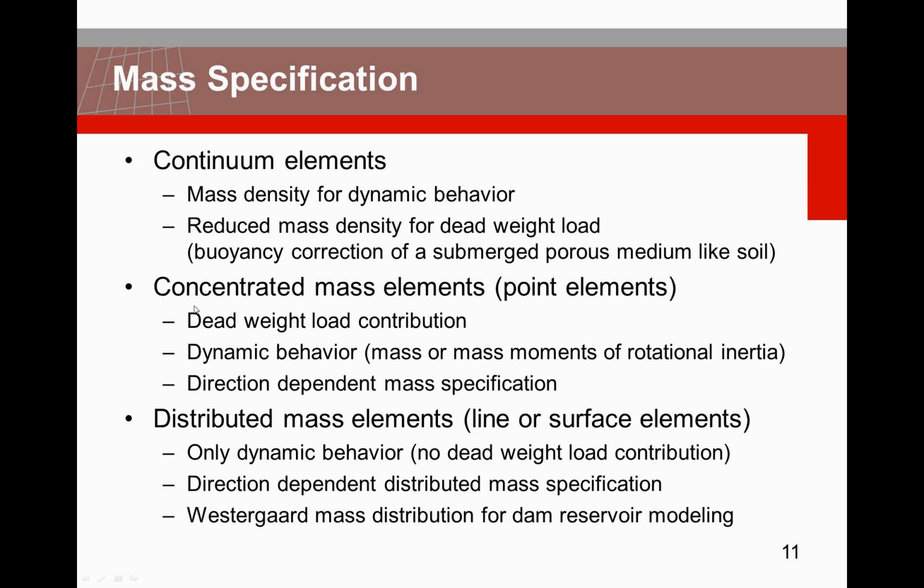Next to the continuum elements, you maybe have dedicated mass in your model, which you can just represent by point elements. They contribute both to the dead weight and also to the dynamic behavior. You can even specify them direction dependent. So if you want to say that this amount of mass will only work in vertical direction, you can specify that by leaving your two horizontal directions 0.